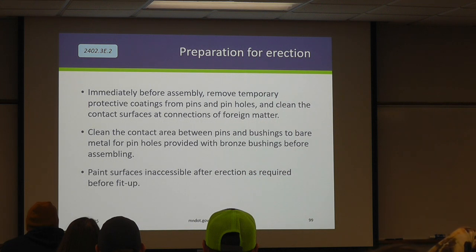90+% of the time, if it's a fixed bearing, you're not going to put the anchorages in, but again, that's something you're going to have to look at with your installation instructions. And just be prepared for those beams to be in place. Set those bearings, make sure you understand where they are.